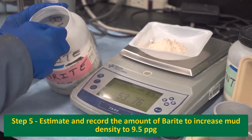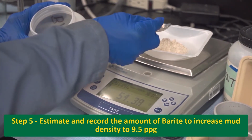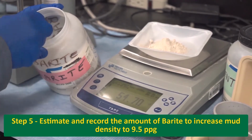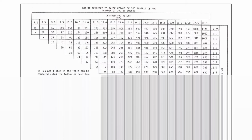Next, estimate and record the amount of barite in grams that should be added to your mud to increase the density to 9.5 pounds per gallon. Use the table named barite required to raise weight of 100 barrels of mud on page 25 of the lab manual. In the report, calculate the exact amount from first principles, in other words, using material balance.